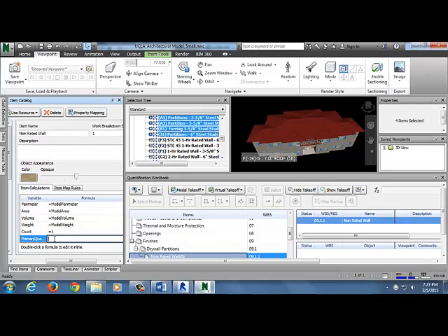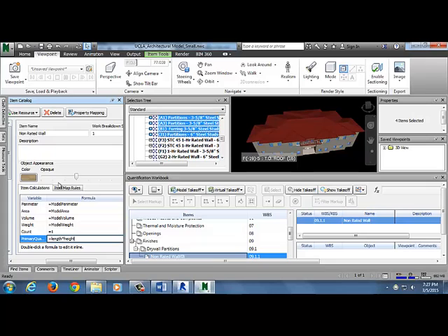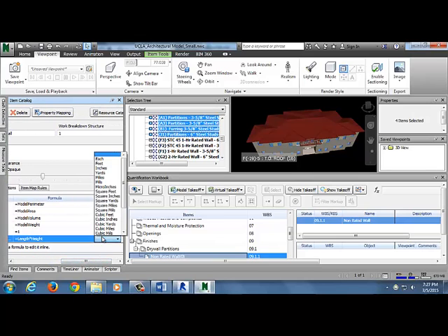So I'm going to make this primary quantity for my non-rated wall equal length times height. You can do either, but because I defined length as equals model length, they're the same. But if I said height equals 6 feet here and just did a hard key, then I could say length times height, and it's always length times 6. So there are two layers of variables there. Okay, so length times height, and then I have to put a unit equals square feet.